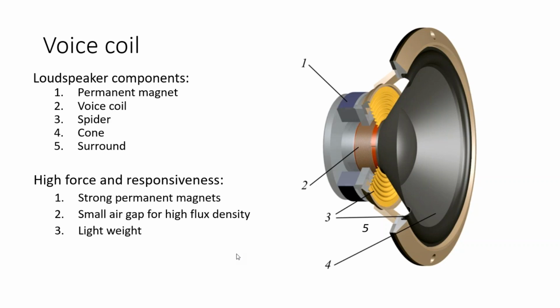Although we won't be dealing exactly with the acoustic interactions, we will show how EMS can help obtain characteristics of the electrical side of the voice coil, as well as the electromagnetic side, which is basically the characterization of the force developed between the voice coil and the magnets.